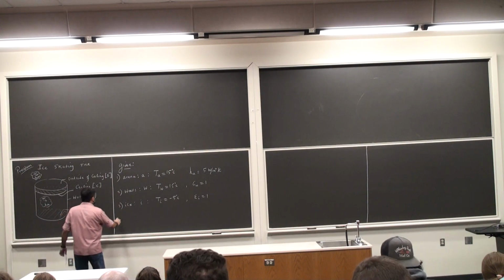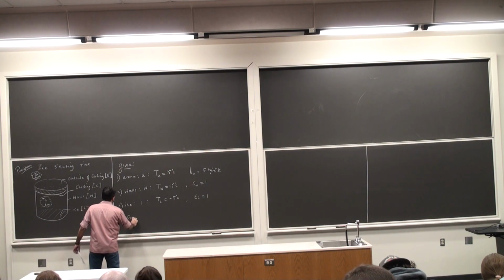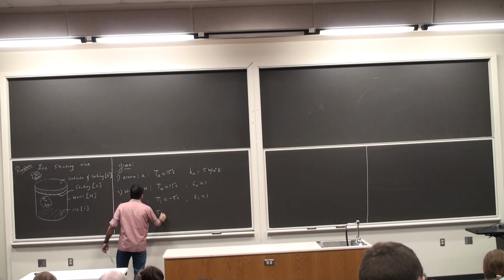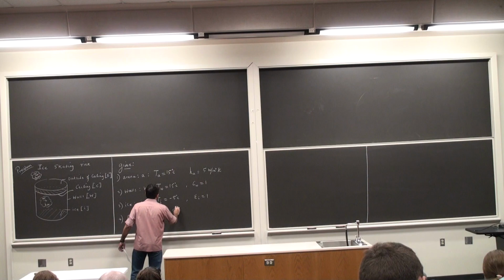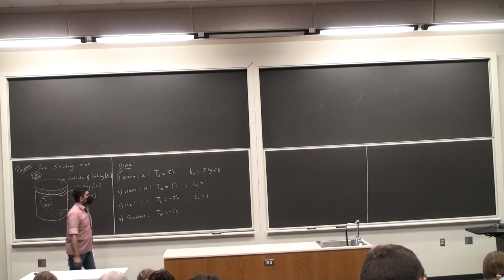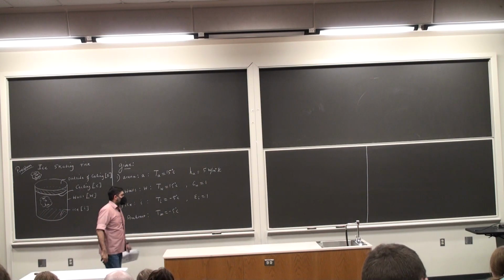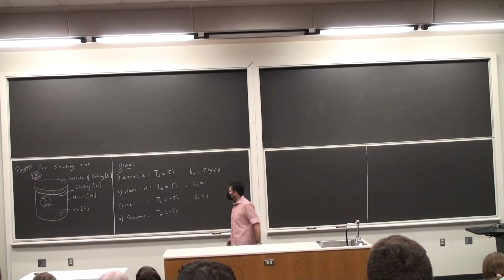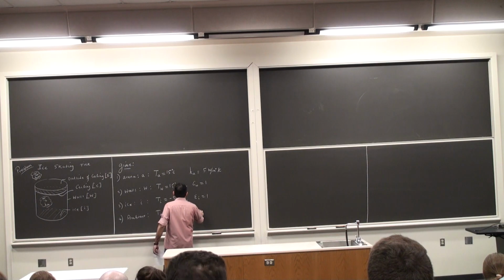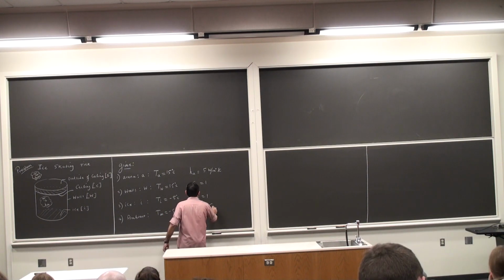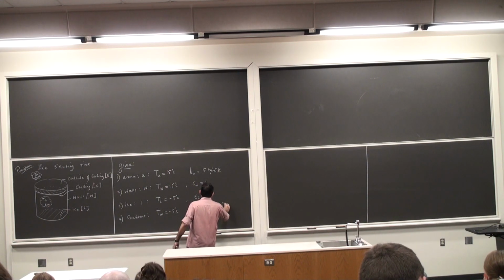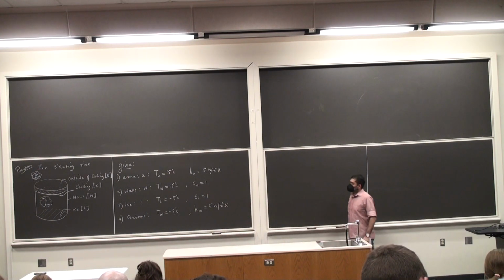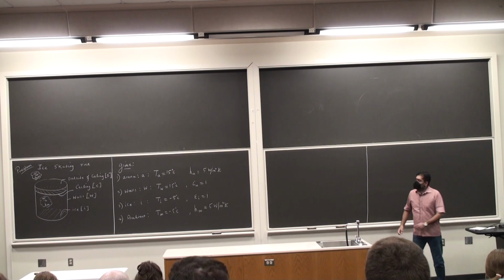So ambient, T infinity is minus 5 degrees Celsius, and h is the same as the inside arena. So there is very slow moving air both on the outside as well as on the inside. So I have h infinity is 5 watts per meter square Kelvin. So that's given to us. And then we have the ceiling itself.